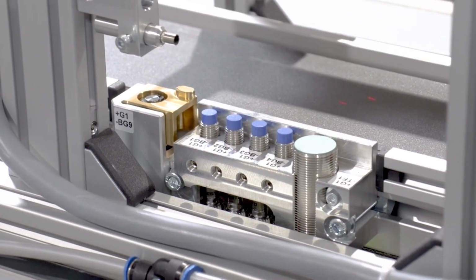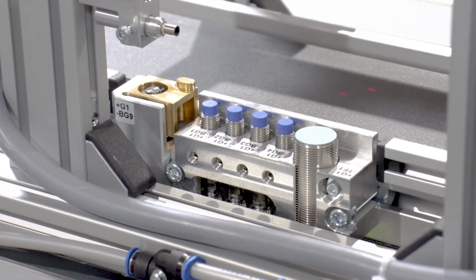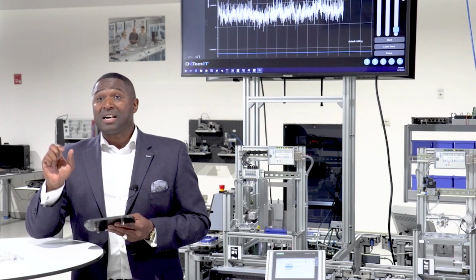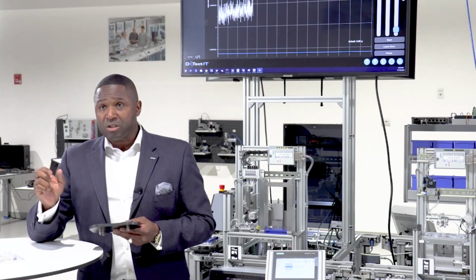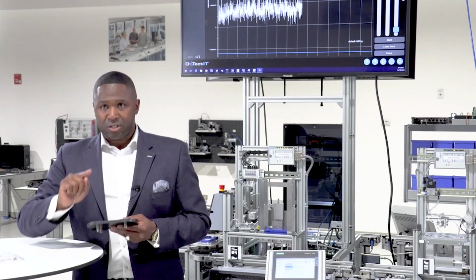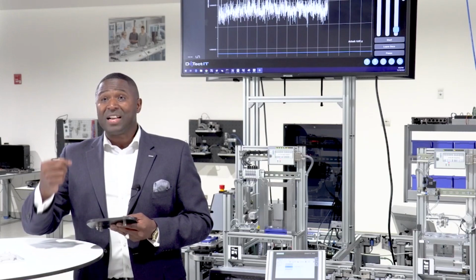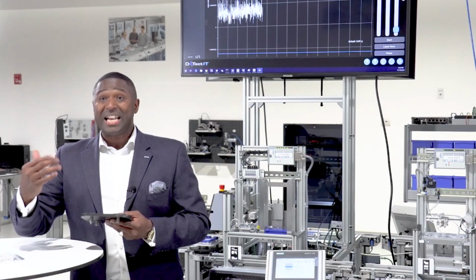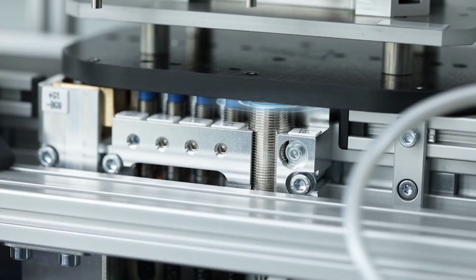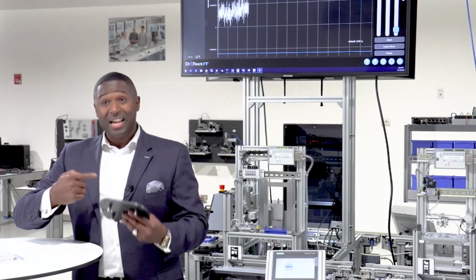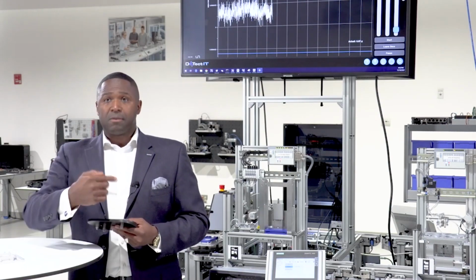The stop gate consists of 4 digital proximity sensors. These recognition sensors allow us to collect binary data in clusters for part type management, as well as an RFID sensor. We also have an air-driven stop gate cylinder, which is basically an actuator that stops the part when it comes in, or the carrier when it comes in, and then allows for us to push and pull that data like we talked about earlier.